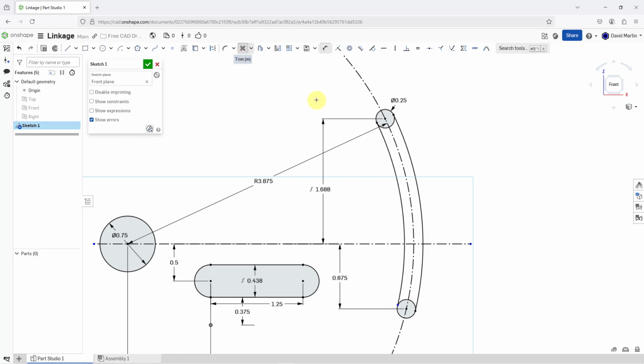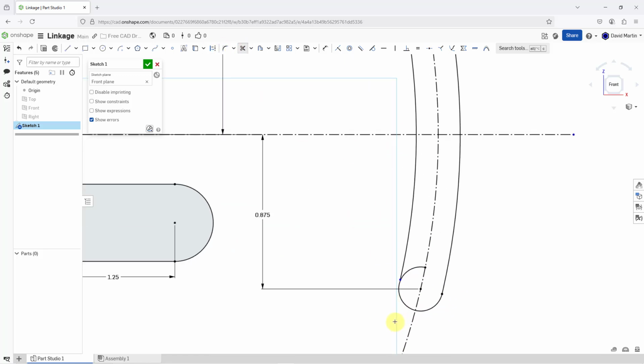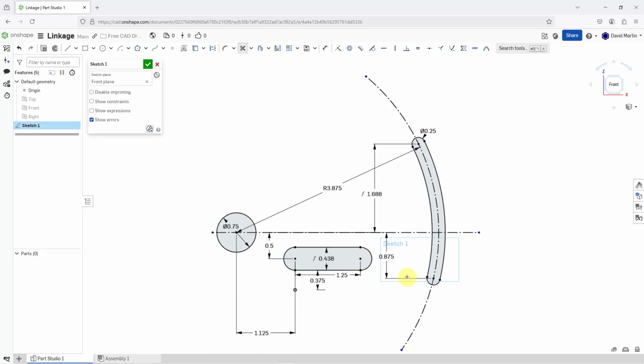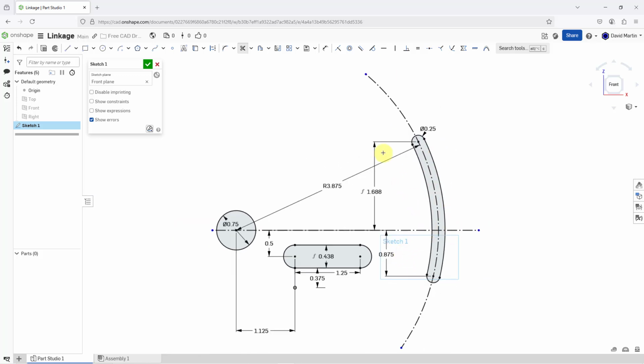Let me use the trim tool to get rid of some of these different entities. Oops. Let's hit the undo button. Let's try using trim again. How's this? That one looks good. Oh, these aren't exactly touching. So let's try, no, trim extend. Extend this to this. Okay, looks like that worked, and looks like a bunch of things turned black. Let's go to trim once more and trim this. Okay, so this actually looks pretty good for the slot.